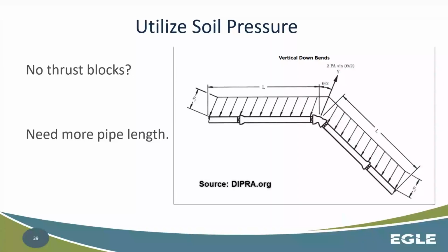If you don't necessarily have thrust blocks, although it's highly recommended, there's ways around that. You need to make sure that all of that thrust force is accounted for. So in that situation, pretty much you're talking about extending that water main as long as possible, so all that force is being distributed along that main. Okay, so it's not just on one point, and this is all loose soil where these joints can be affected.